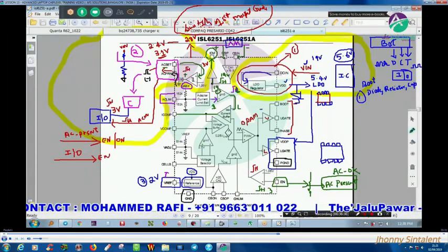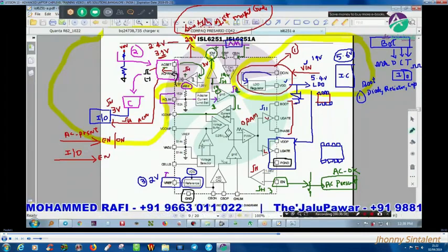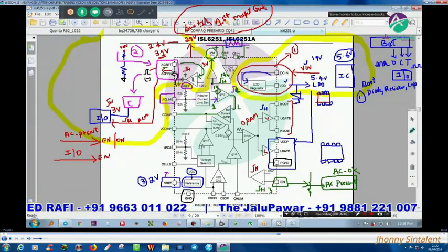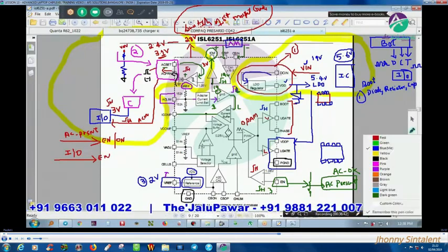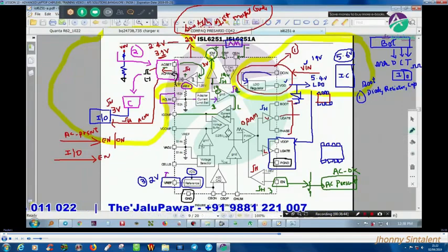Okay, so here I will have a high voltage. Lower gate, that means this line is connected to my lower MOSFET gate. The upper MOSFET drain is connected to my VIN. Okay, so I have a boot pump, I have a VIN voltage, I have lower gate also.